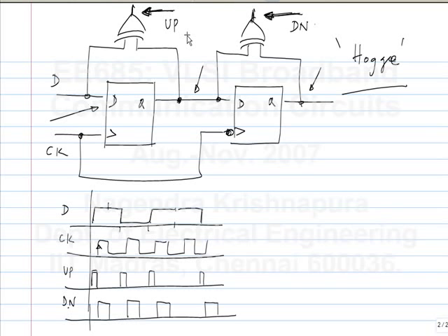So that we define as a transition density of 1. Now, random data will have a transition density of half. Every bit can be either 0 or 1. That means that if this bit is 0, the following one can be either the same bit or another bit with equal likelihood. So the transition density is half. And similarly, you can arrange the data to have different transition densities. So what is the effect of transition density on the clock recovery circuit? What do you think will happen?